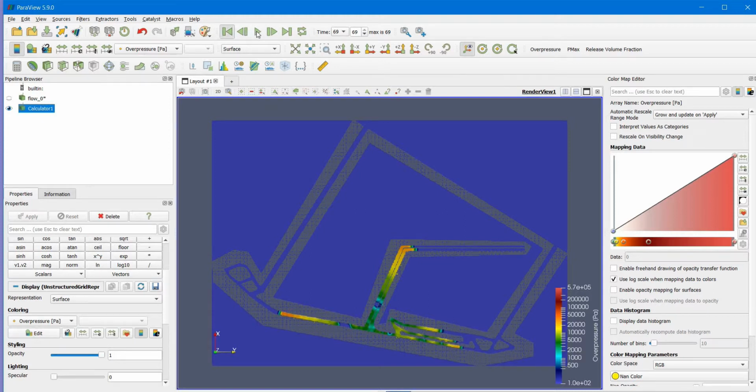But before we do that, let's just take a look at our gas explosion. So this is the pressure, and you can see you got a significant overpressure here, maybe 4, maybe 6 bar. You can see the shock wave or the pressure wave propagating through the mine shafts. And if you keep going, it'll come out the other end. But it certainly has shown that we need to model a dust explosion that would probably ensue from this. And so we'll go back to exploCFD and set that up.